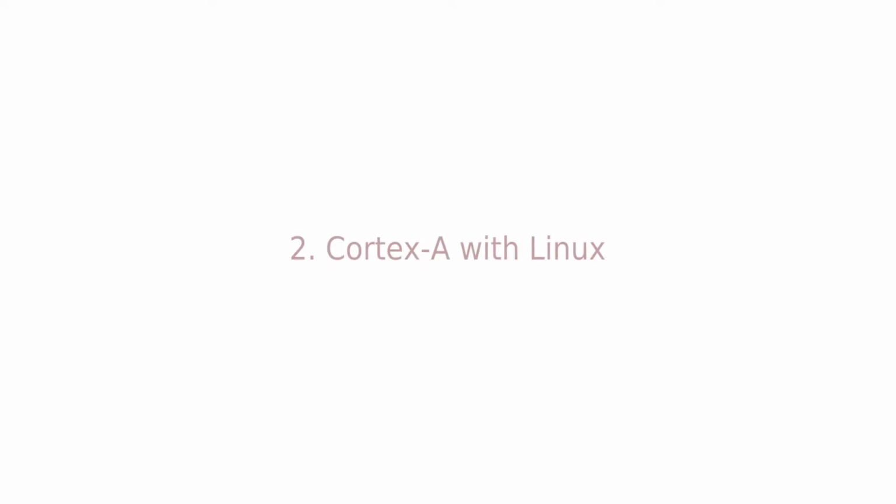Also, supporting complex communication protocol stacks like USB, TCP/IP and different security layers without a feature-rich OS like Linux is difficult and expensive. The second option is to move to the Linux world. Place everything in a Cortex-A core. On the plus side, you get the feature-rich OS. The question is how well your real-time requirements can be handled and how difficult it might be to port your application to run under Linux. Yes, there are real-time versions of Linux. No, they are not just plug-in solutions. You need to dig deep and have full control to make it work.